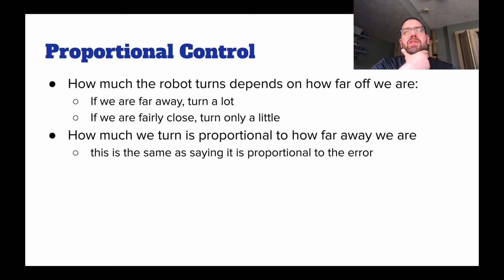So part of what I'm saying is let's start with proportional control. And what we mean by that is the controller is just going to be a gain, just some letter K that's going to multiply the error by K to turn it into the voltage that's going to the motor or whatever. And what that means is the farther away from the wall or the line I am, the more the robot is going to turn.